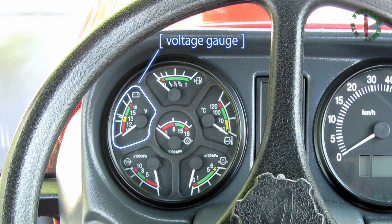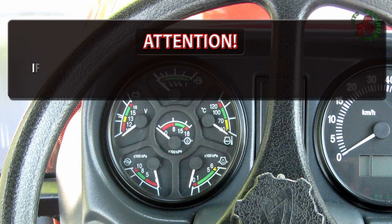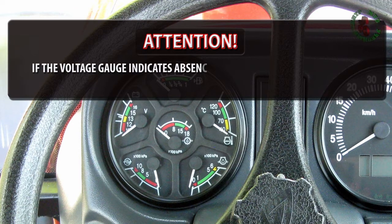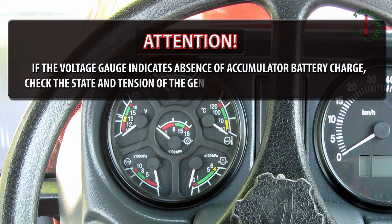Voltage gauge indicates accumulator batteries voltage with the engine stopped, with the key of starter and instrument switch set in position 1. With the engine running, the voltage gauge indicates voltage on generator terminals. A pilot lamp near the voltage gauge lights up in case of problems with the additional battery charge. If the voltage gauge indicates absence of accumulator battery charge, check the state and tension of the generator drive belt.